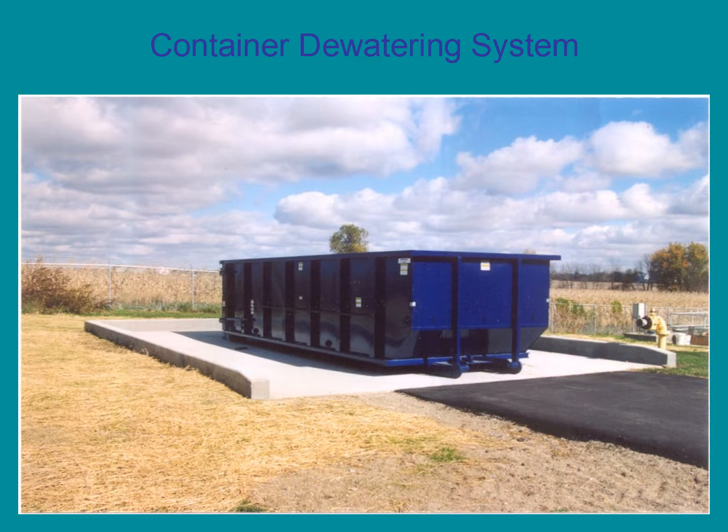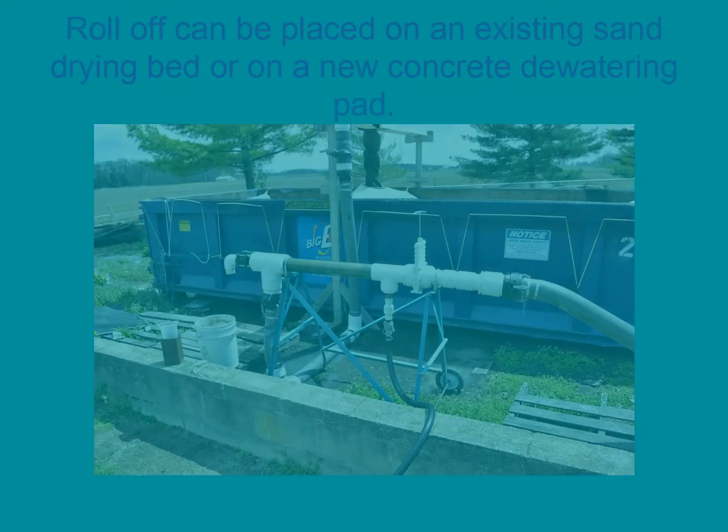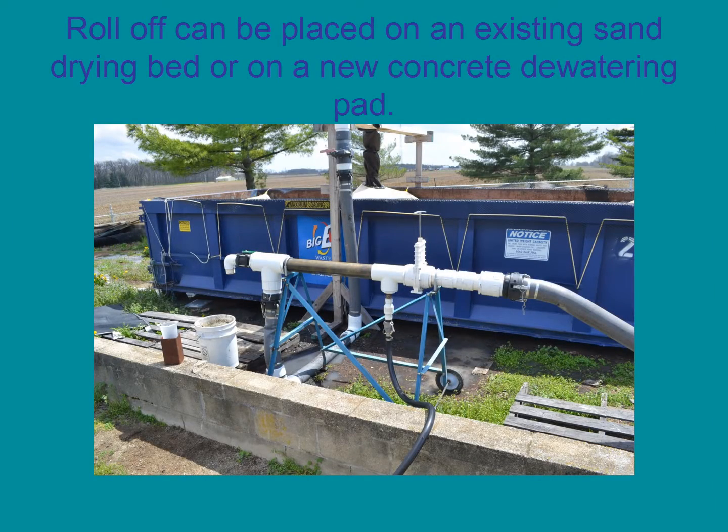The geotextile container bag process can be used in those plants where the sludge is intended to be disposed of in a landfill. The bag is sewn in a bread box shape to fit into a variety of landfill containers. In this case, the container is a standard landfill roll-off container.